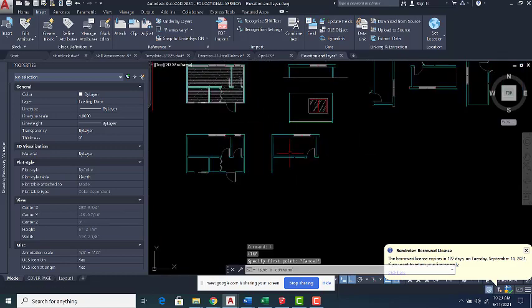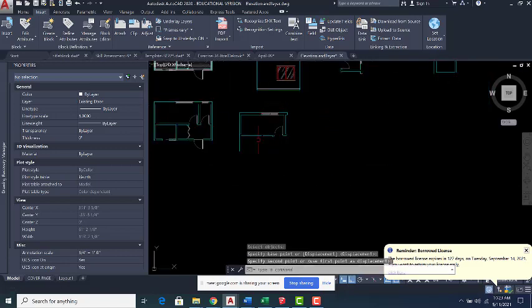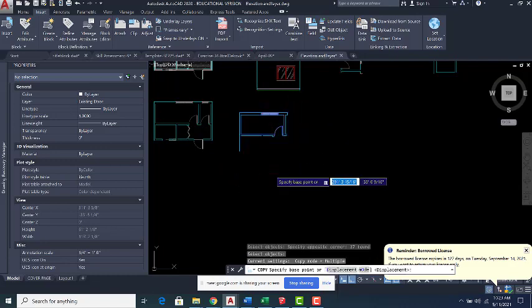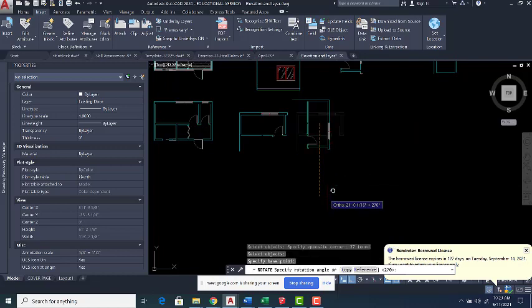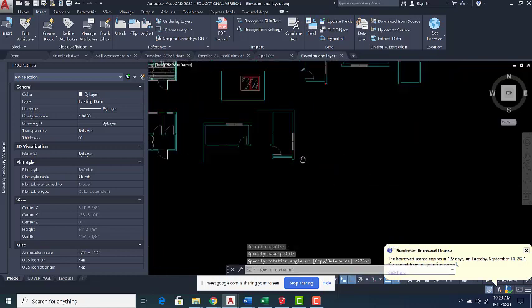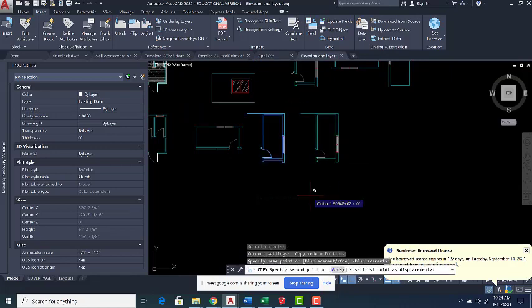So when I copy, the fastest way would be, before cutting anything, I would copy this one 4 times. And each time I would rotate it once. This is the fastest way, I copy this one here, then I rotate it. See, select kind of the middle of this one, go down, it would be 90 degrees. Then I copy again the same object, bring it here, rotate it,